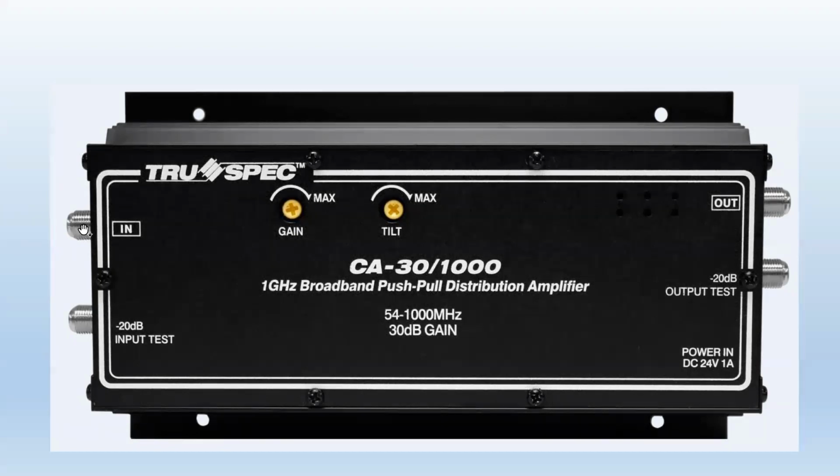So the signal will be displayed not properly, and if it's too strong, the tuner might get damaged. So if you want to take a sample of what's coming in, you just connect your TV to this one here, because the signal is lowered by 20 dBs. That's what's on the input, and over here, same thing. What's on the output is lowered by 20 dBs, and you get your test sample on the output.